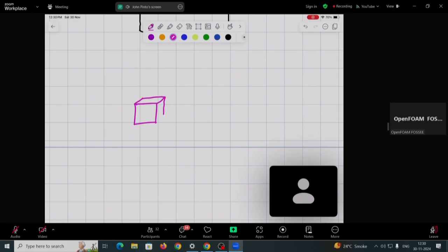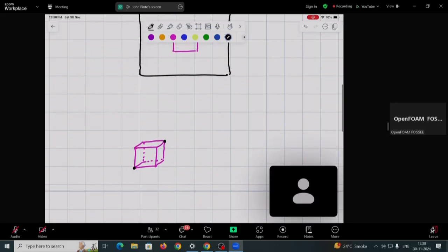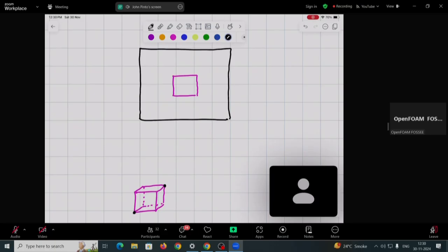So the heater is actually something like this, in 3 dimensions. Whenever we specify the box to capture the cells, we need to specify these corner points 1 and 2. When we specify these corner points, it will consider that to be a zone, and all the cells that lie within that zone, it will select. That is what the first command did: box to cell, which we created into a cell set, and that cell set became the heater. So the pink one is done.